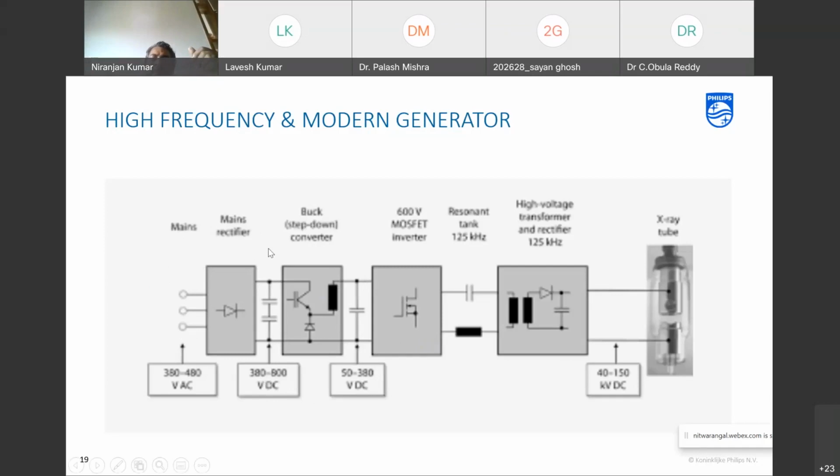Okay, for example, one of the techniques here is that in place of a fluctuating DC bus, we can use either a PFC or buck converter to make a stable DC. And then here you can control the DC itself, and this is a high voltage high frequency inverter, so it is a high frequency AC, and with that high frequency AC your actual transformer becomes very small and you do the same thing.